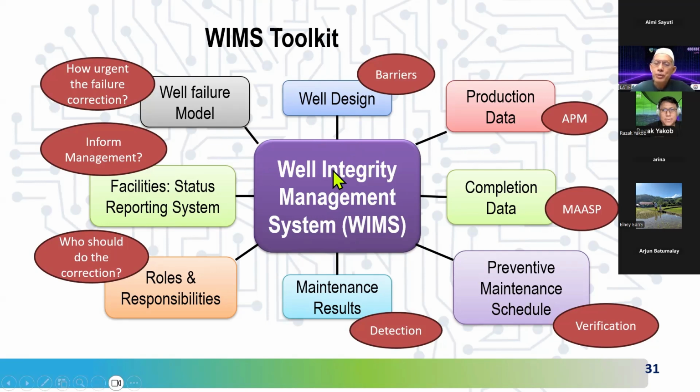So as you go, the production management will have the production data showing the water content, the water production that is coming in. You're going to have production data with pressure and temperature coming in, and so on. So annulus pressure management will happen also over here. When we have the completion data, of course, you have to look at the annulus pressure with the maximum allowable surface pressure. It is one of the keys to monitor the stresses at the surface around the wellhead area. And then preventive maintenance, you have to do some preparation.